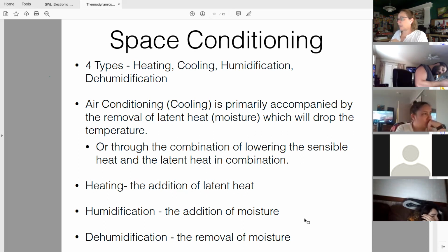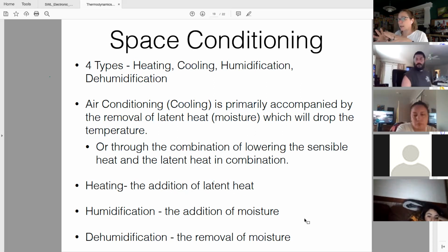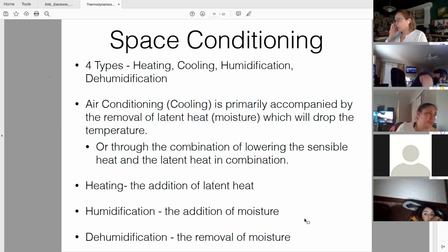Passive cooling, another method, is like a courtyard with lots of vegetation. Plants are giving moisture off to the air, and so that can help cool down your temperature. If you think of really hot climates, they often have a courtyard, and then the addition of a fountain. And this is where we talked about evapotranspiration the other week, of adding moisture into the air, again, in more dry climates.